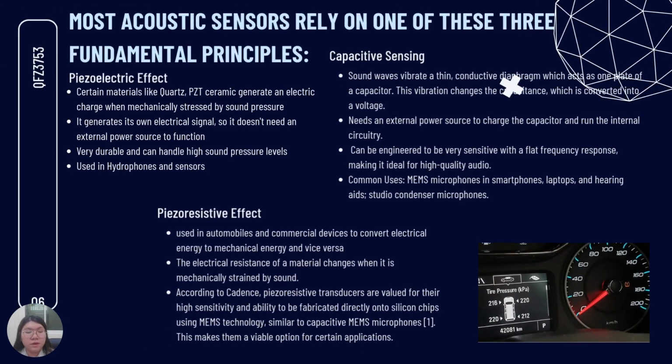This can be classified into three fundamental principles. The first is the piezoelectric effect, where certain materials like quartz and piezoelectric ceramic generate an electric charge when mechanically stressed by sound pressure. It can generate its own electrical signals, so it does not require any external power source to function. It's very durable and can handle high sound pressure levels.